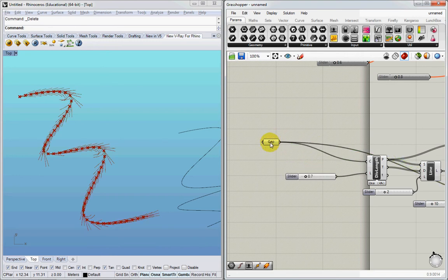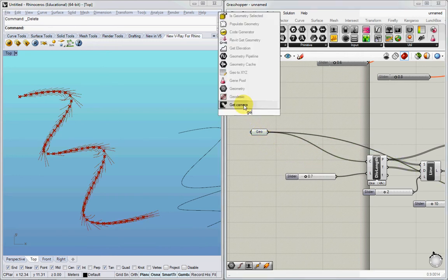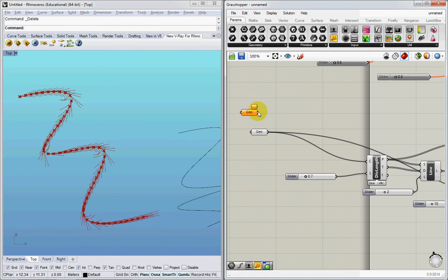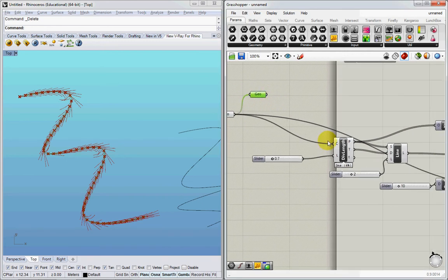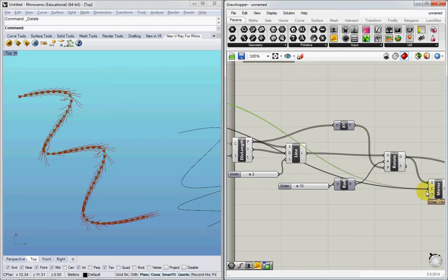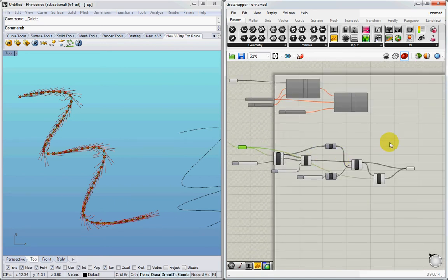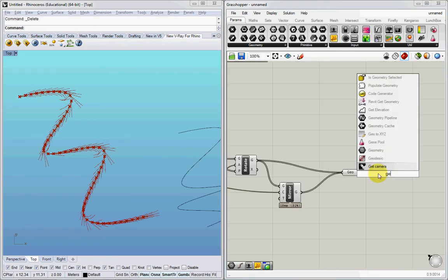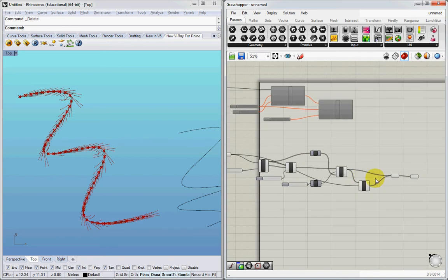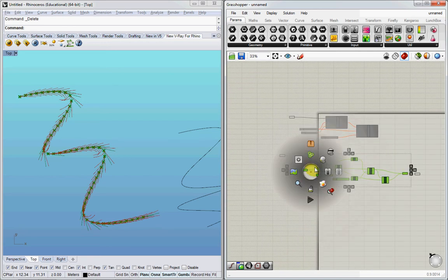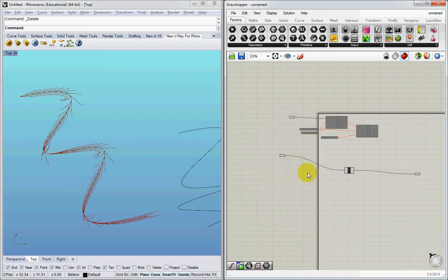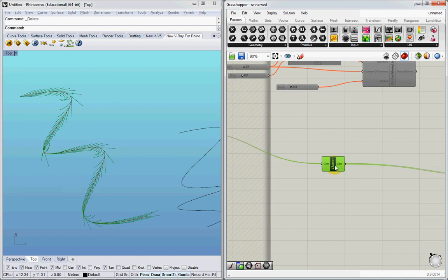As a general rule, when you're clustering, you don't want to have this kind of split. So I'm going to add this in here, and this will plug into that, and that will then ferry our geometry into these nodes. I'm going to grab everything together, add that there too, and cluster it. So here we've created another cluster.